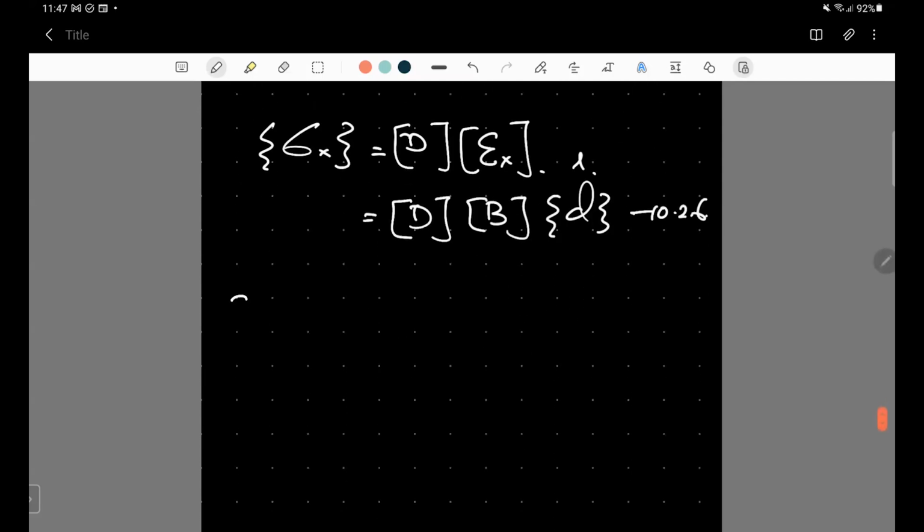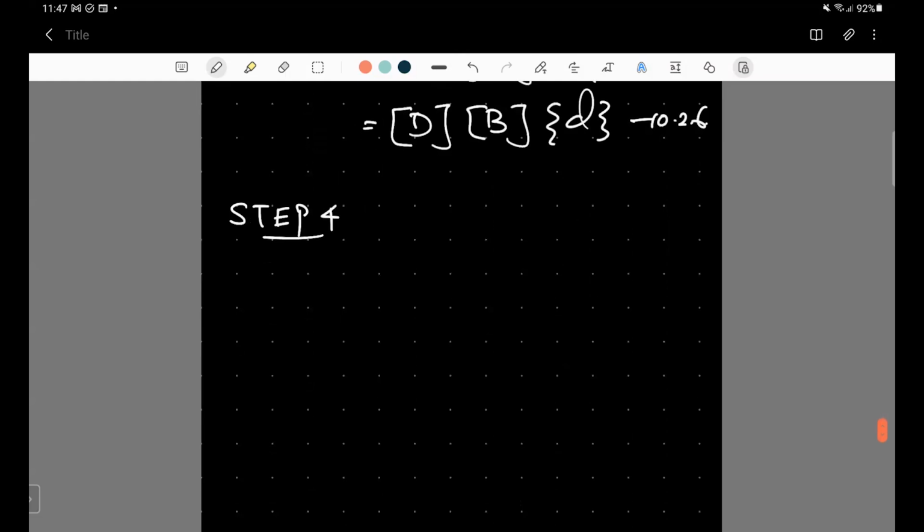In the next step, we have to derive the element stiffness matrix as well as the mass matrices and corresponding equations for this particular problem. We know the bar is not in equilibrium because it is under a time-dependent force. Because it is not in equilibrium, F1x is not equal to F2x. Therefore, we can again apply Newton's law of motion, which is nothing but force is equal to mass times acceleration.